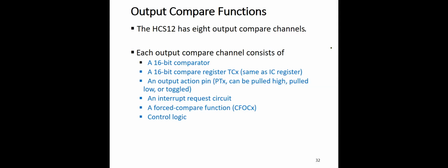Okay. All right. The other timing functionality that comes with this timer system inside the HCS12 microcontroller is basically the output compare functionality. This is very similar. If the input capture is similar to the stopwatch operation, the output compare is basically similar to the alarm operation that we have in our watches.